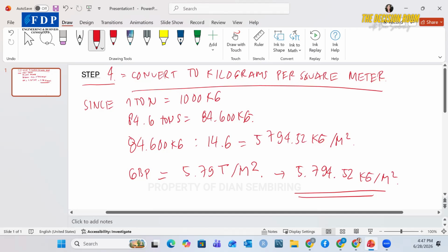When the crane lifts a load, the weight shifts toward one side or toward the front of the crane. This means one crawler track usually carries more load than the other. So the actual ground pressure can be significantly higher than this simple calculation. For engineering design and lift planning, manufacturers provide ground reaction load or crawler track reaction in the crane load chart. These values should always be used whenever available.